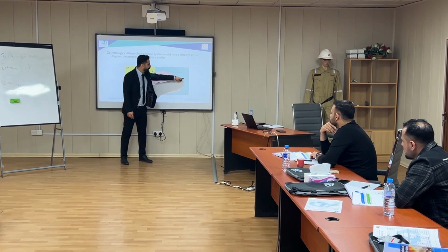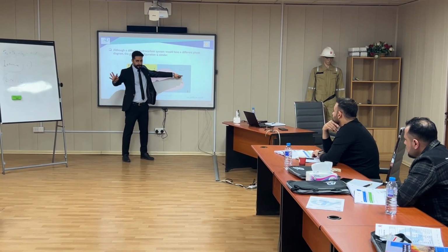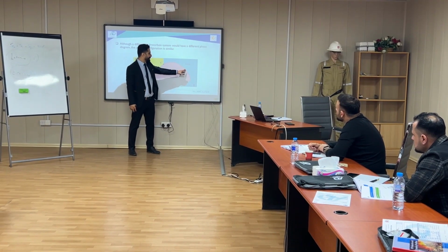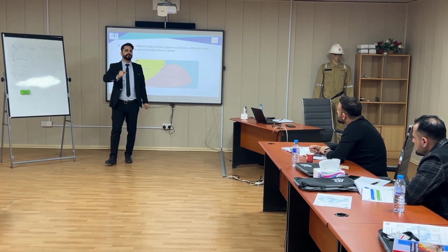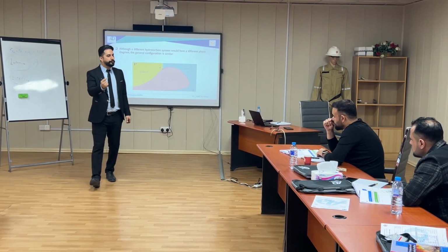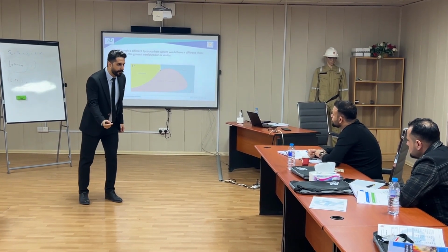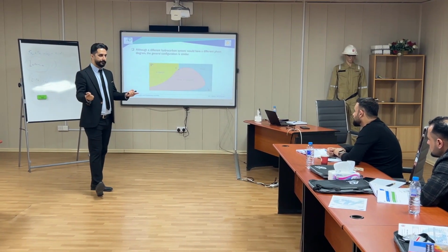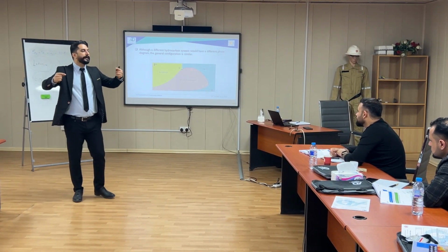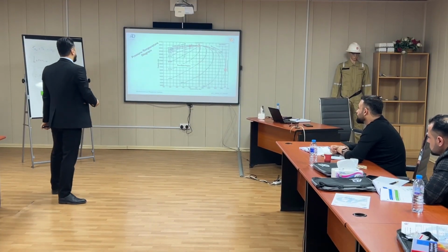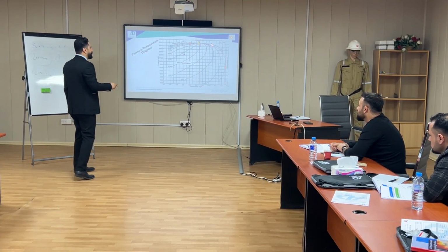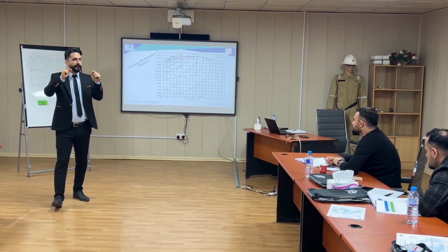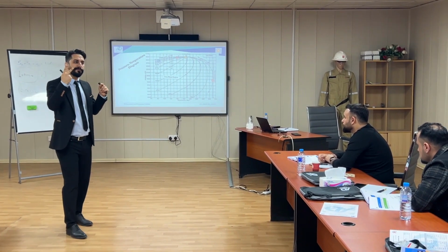Okay? When temperature of the gas at constant pressure is going to be decreased, we will reach to this line. And first droplet of the liquid at dew point line is going to be formed. Again, we are going to enter the two-phase region. That's why bubble point line and dew point line are important for us, because when we reach to them, we are going to experience two-phase fluid.